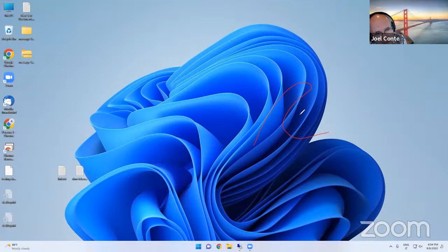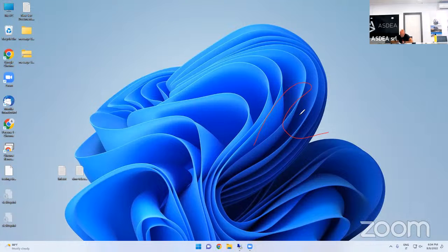The snap through and snap back, right? Combined. So exactly, the arc length works on the concept of, imagine you are here, you are searching around this incremental arc length. You typically have a couple of solutions. One of them is the loading path, because it is going in the loading direction. The other is the previous path. So you typically discard this point and you go in this way.